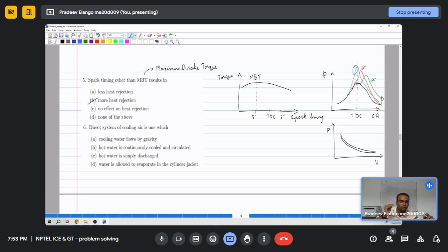So while you are compressing, when you are supplying flywheel energy to compress the gas, you have started combustion, and there is more and more pressure and more resistance for you to compress. Because of that, you cannot have maximum power or torque, and that is why there is an optimal timing.